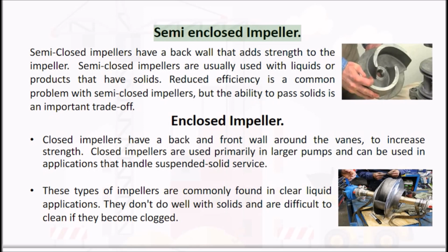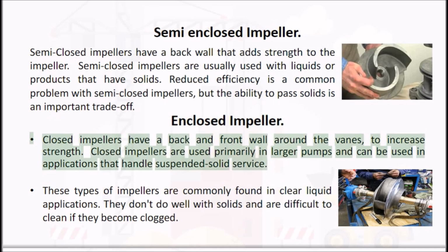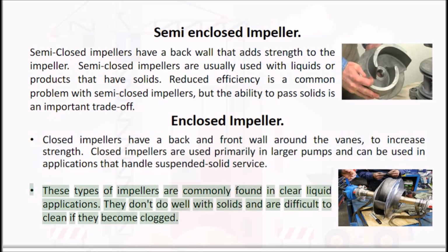Semi-enclosed impeller. Enclosed impeller. Closed impellers have a back and front wall around the vanes, to increase strength. Closed impellers are used primarily in larger pumps. These types of impellers are commonly found in clear liquid applications. They don't do well with solids and are difficult to clean if they become clogged.